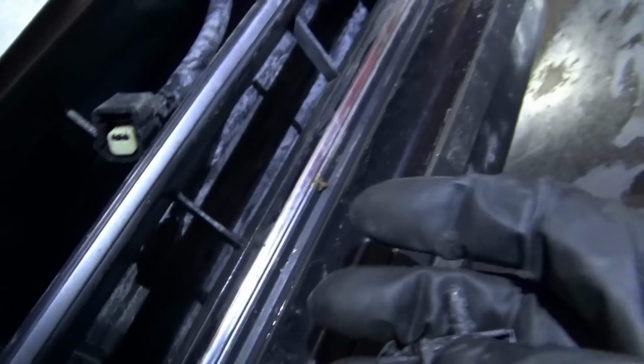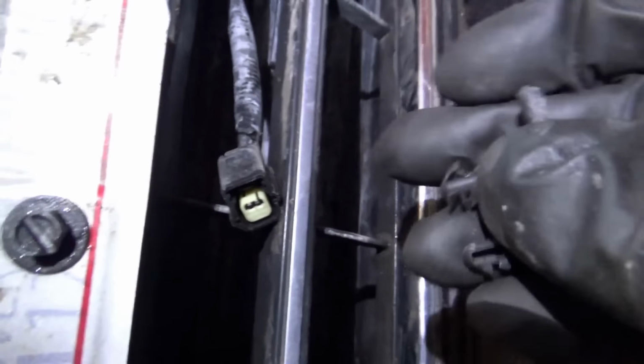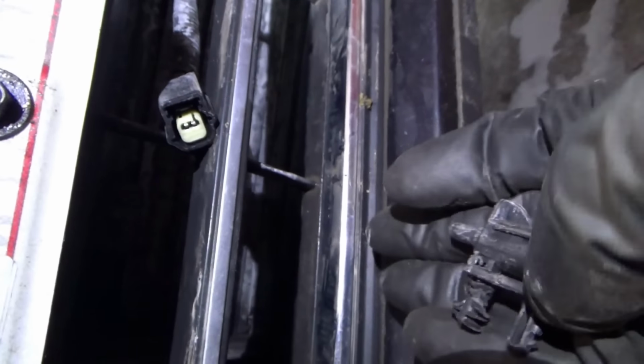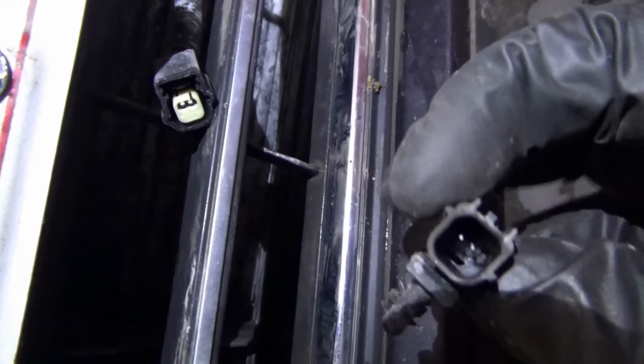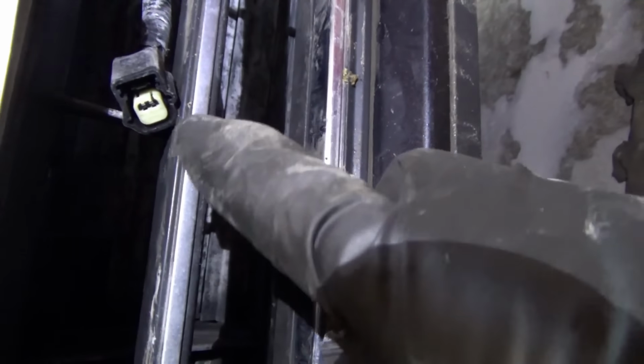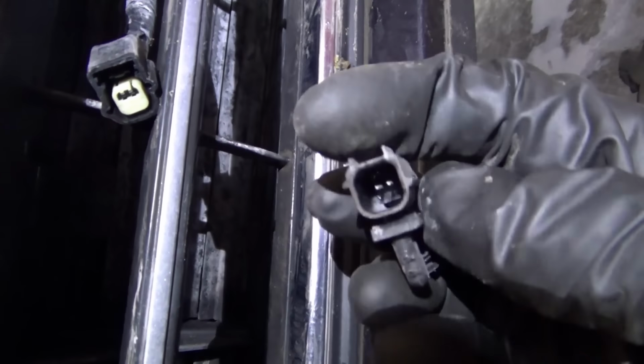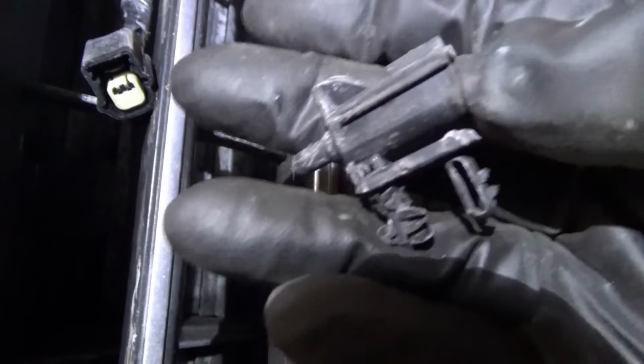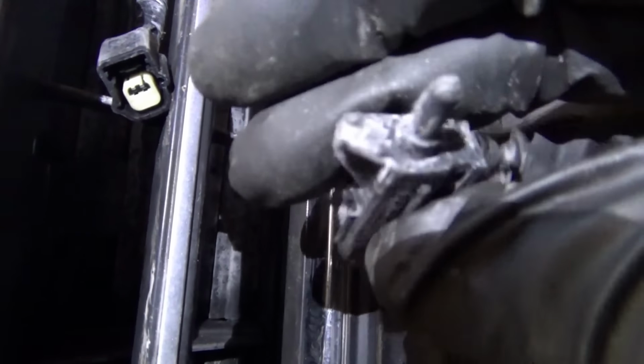Alright, so I managed to extract the ambient air temperature sensor. It lives right here, so the grill spaces are big enough. You can stick a claw through there. There's the connector. Here is the sensor. Let's measure the resistance of this sensor, and then we could just use a decade box to kind of trick the computer into thinking we're at some normal ambient temp. Make sure the circuit's good. It's probably just a bad sensor.